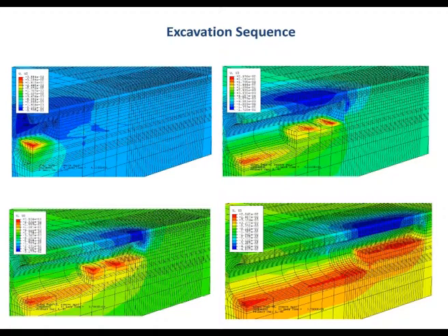But the shotcrete over here on this side is more permanent, and so they are about 150 to 200. And then there are steel bulkheads, not just steel bar, but steel frames, which are cast into the shotcrete. So, steel sections, like I-beams, but they call them bulkheads, which are cast into the shotcrete. So basically, you put in the steel first and then spray the shotcrete over it, so as to completely embed the section. The final lining we didn't analyze because it took place much later, maybe 100 days later or something like that.